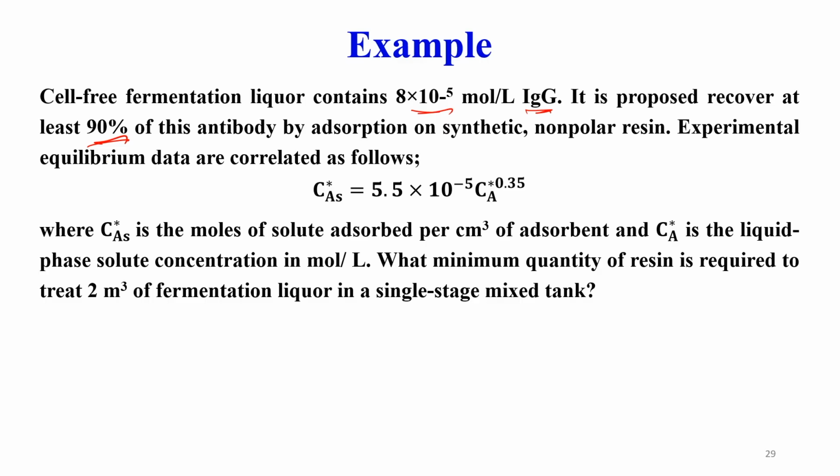The experimental equilibrium data is correlated as follows: C_AS, the moles of solute adsorbed per cubic centimeter, is given by 5.5 × 10^-5 C_A^0.35, where C_A is the liquid phase solute concentration in mole per liter. What is the minimum quantity of resin required to treat 2 cubic meters of fermentation liquor in a single stage mixed tank?